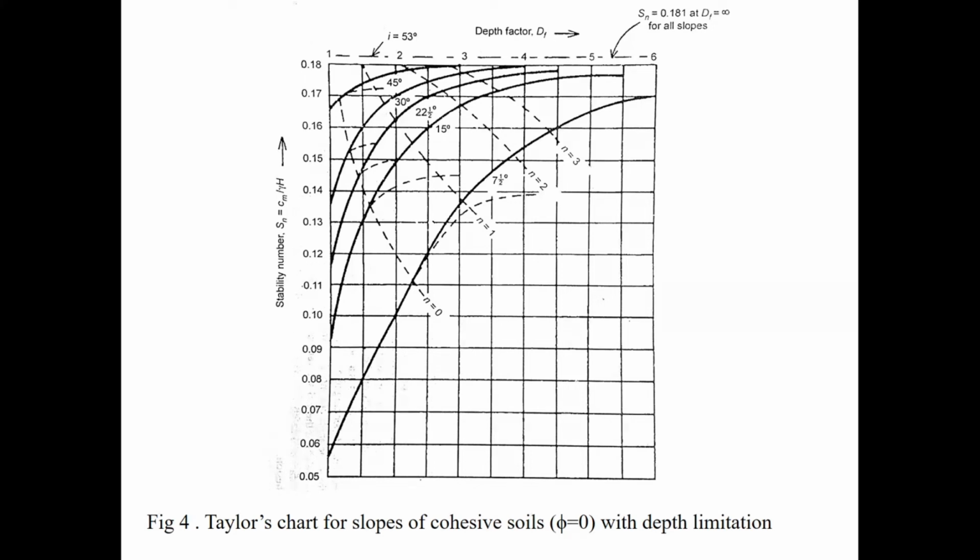30.96. And what is the maximum cohesion this soil can have? What is the cohesion of this soil? 27, right? So is that possible? What is the factor of safety with respect to cohesion here? 0.872. So that is less than 1, isn't it? It is not even near 1.5. It is even less than 1. So definitely it's not stable, right? So hence it is not safe.